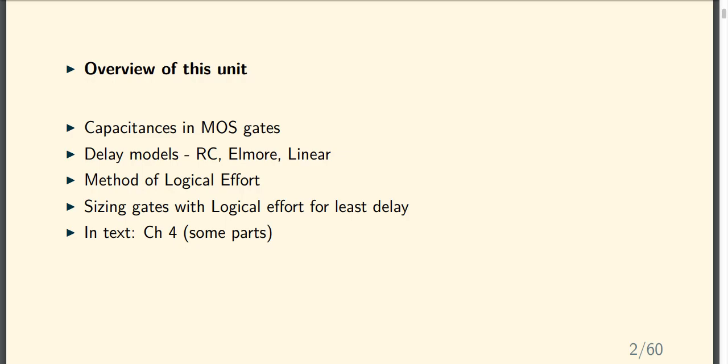As the first iteration, the Elmore delay can be used to calculate the delay because it gives us a very good number, almost 90% close to the actual delay, but it takes a much smaller amount of time. As we know, verification is a very important part of the VLSI design flow. So if I have some model that can give me the delay in a much quicker amount of time, that is very good for me. So Elmore delay is one such model.